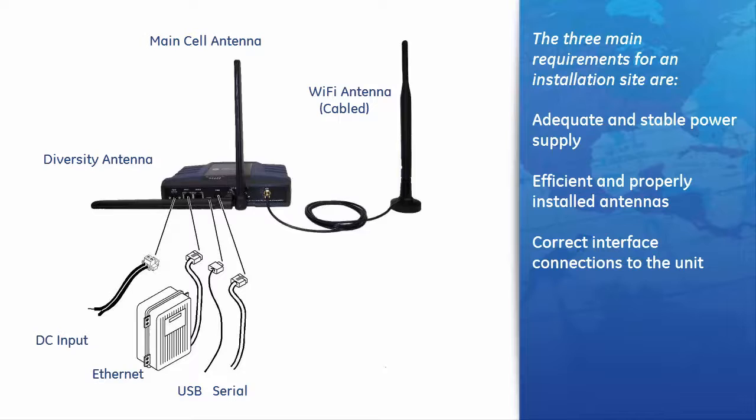When connecting antennas via cable, the length of coaxial lines should be kept as short as possible, and care should be taken not to pinch or kink the coax at any point along its run. The cable should be of a type suited for the frequency of operation to minimize signal loss. Again, more details on cabling are provided in the product's documentation.